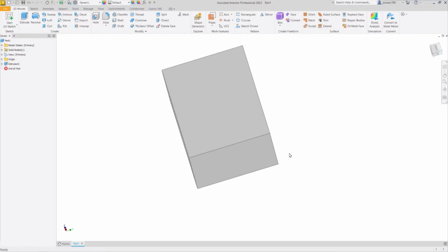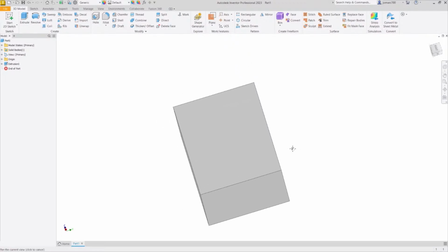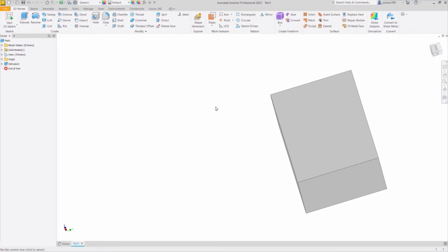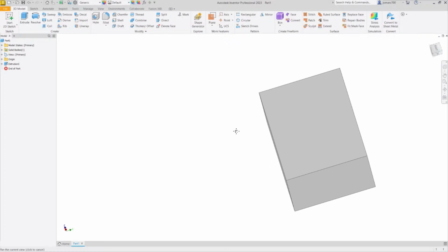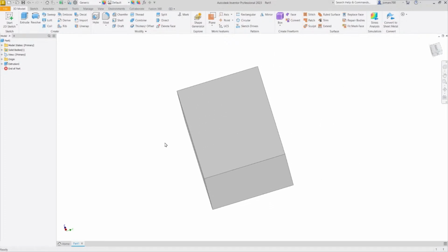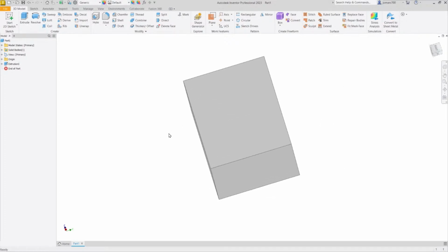Next, also same with AutoCAD, to pan our way into Inventor, it's simply holding our scroll wheel. So notice once more the change of our icon. It turns into a hand. From here, I am now panning my way into this 3D object.